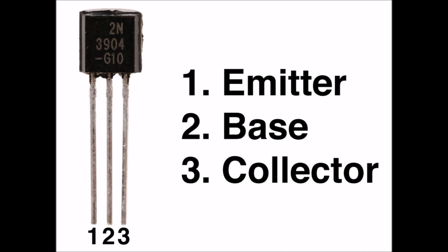A bias. Distortion. Distortion in electronics: undesired change in an electric signal waveform as it passes from the input to the output of some system or device. In an audio system, distortion results in poor reproduction of recorded or transmitted sound. Nonlinearity. In an electric circuit, a nonlinear element or nonlinear device is an electrical element which does not have a linear relationship between current and voltage. A diode is a simple example. The current I through a diode is a nonlinear function of the voltage V across its terminals.